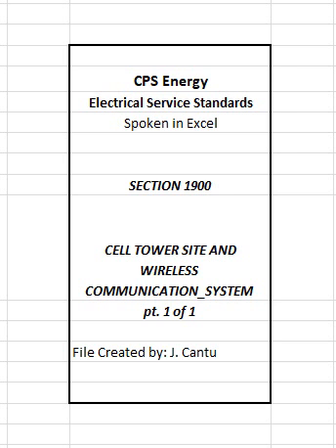Customer meter pole shall be located at an approved location on customer property or a pre-approved location on public right-of-way. Note: pole installation shall be in accordance with Section 1400 and wireless communication equipment shall be installed in accordance with figures 1903 and 1904 and pole attachment standards, refer to helpful numbers listed on the inside front cover page.